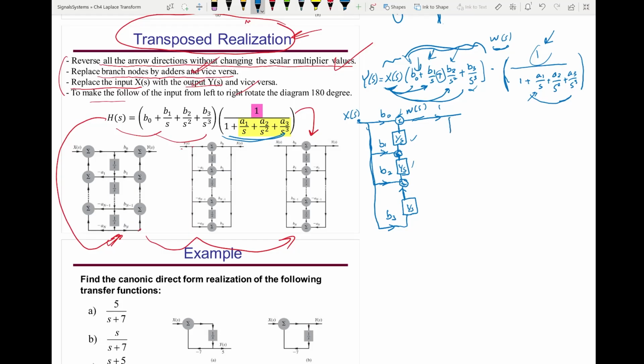So then it's going a1 negative, and integrator 1 over s will be here. 1 over s and goes here and back here. Then it goes to a second integrator and amplified by a2. So this negative feedback, that's minus a2.